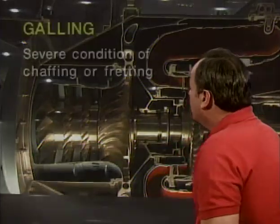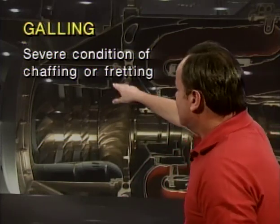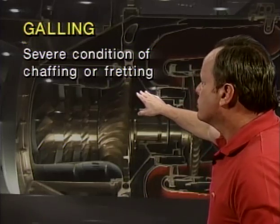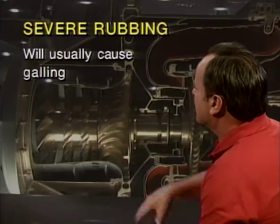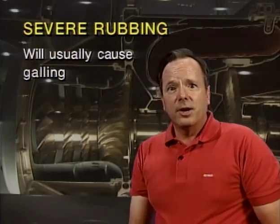Now, here's a concept they're going to ask you about, and that is if you have two parts rubbed together, what would it be called? And that would be called galling. My mom used to always use that term. That really galls me, and it's the same thing. Things are rubbing together, and it's a severe condition of chafing or fretting, and that's called galling, and it's a transfer of metal from one part to the other. So severe rubbing of turbine engine compressor blades, if you had this in the compressor section, if they rub against the outside, it would cause galling. It would be a very, very bad thing.